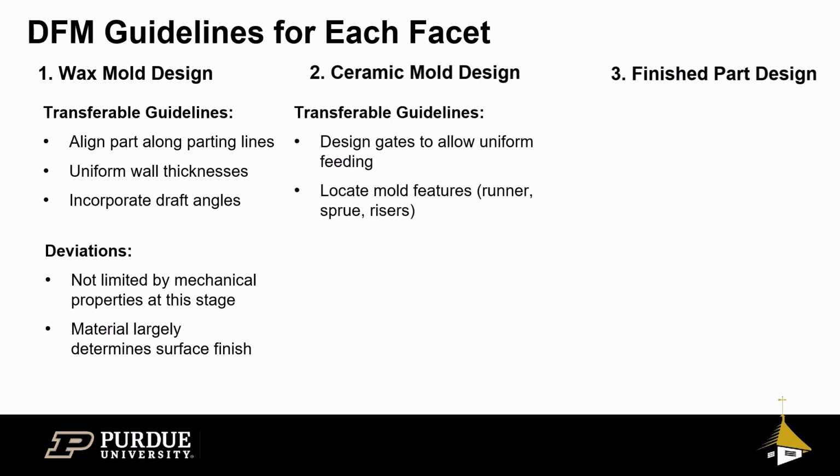For stage 2, we look at the casting guidelines. Designing with gates is still applicable, although the reason is slightly different. A runner will always run downward axially through the tree mold, and the number of gates required for one part in the tree will need to be replicated throughout the entire pattern. This impacts the pattern density that fits into the tree mold.